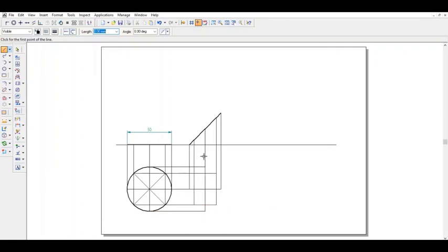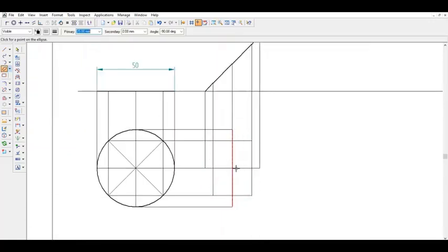So how you are going to proceed further is, you just go for ellipse by 3 points. Go for ellipse by 3 points here. Now select from the topmost portion either of the diameters, the major axis and minor axis. So let us say I am selecting this particular point here, from here to here. Now let me just zoom in here. I don't know whether it is going to cross through all points or not, but in most cases it will go through all the points.